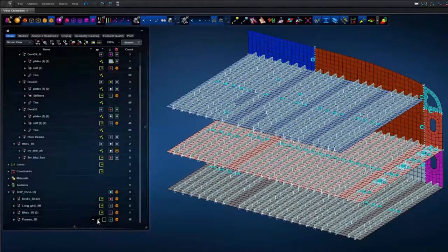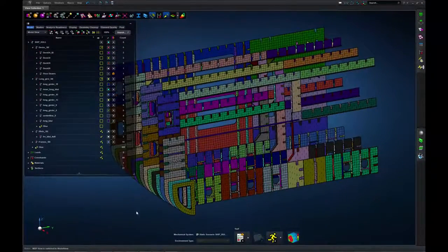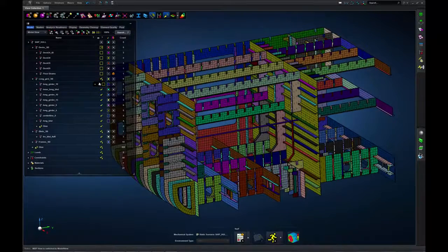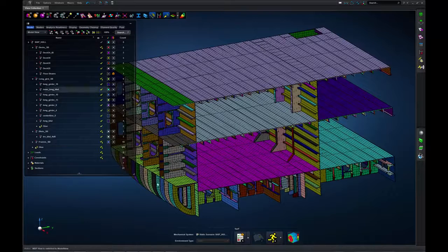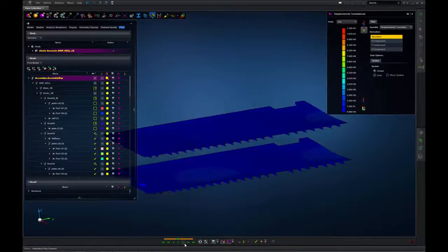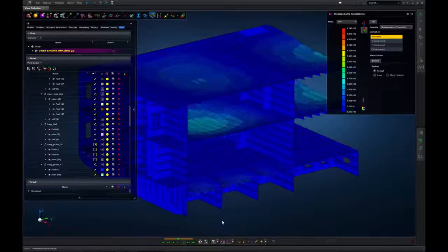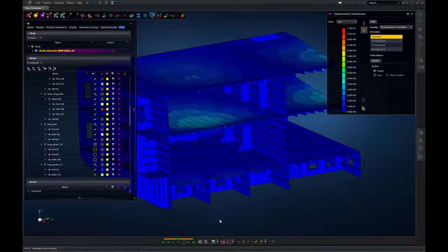MSC Apex is a parts-based solution. Both the user interface and the solver methods are parts and assemblies aware. Engineers can then adopt a divide and conquer approach and incrementally build and validate their models, starting with parts, then subassemblies, before building the complete assembly. Also, the parts-based solver generates parts individually and reuses unchanged parts during incremental runs, which speeds up execution.